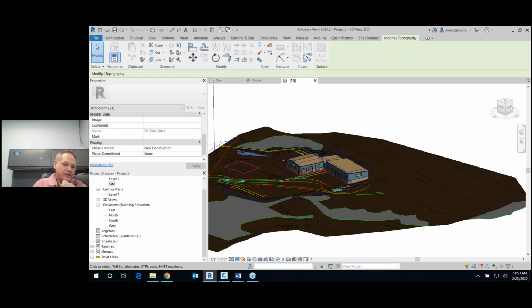For coordination, I like to have my survey point at a benchmark location with the correct elevation. That way, if I am doing an overall campus and I have multiple buildings on a site, I know what those elevations are, because they are being shot from that survey point. So I like to be as close to the civil process as I can be, because acquiring and publishing isn't going to physically move them.